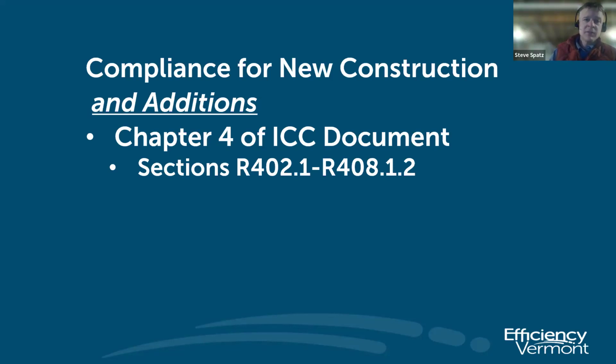So what this means is that if you're building what would be defined as a single-family residence, in the context of what the code requires, you are required, as this state statute has defined, to meet the requirements of the Residential Building Energy Standard. And the Residential Building Energy Standard is updated on a typical 3-year cycle that aligns with the ICC's updates to their model codes of the International Energy Code. And it dictates for anyone building residential buildings or retrofitting them here in Vermont minimum performance standards for a lot of factors on the building, but really the building envelope, mechanical systems, heating and cooling, the physics side of the equation for residential construction.